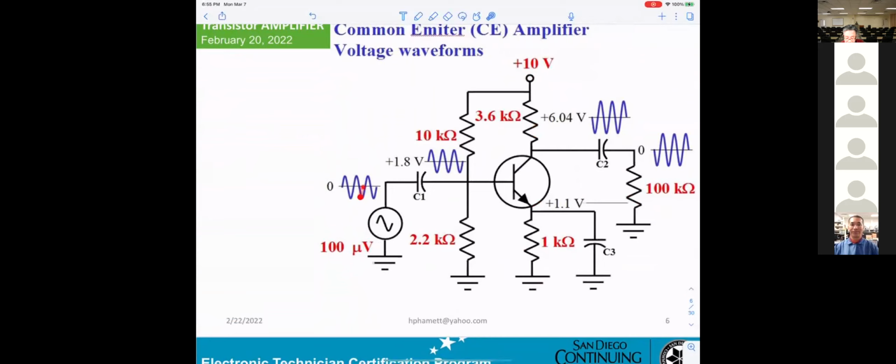You get the sine wave here. Okay? And also, they give it to you. This sine wave will go to here. However, at this point, you get two voltages. One will be the bias, VBB 1.8 volt. And this will be your sine wave signal. Okay, when you're working on your lab, you measure at this point. You can see you get two signals. Okay.